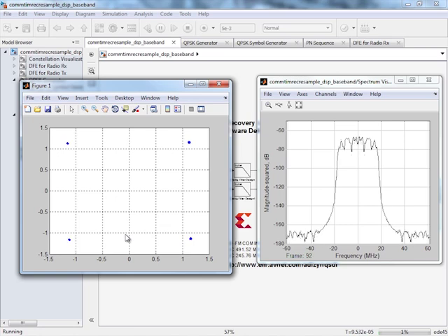However, a real communication system includes data converters as well as the accompanying analog circuitry, including RF transformers and analog filters. The analog signal is also affected by the channel, whether over the air or even just looped back through cables, as we're doing in this demo. Furthermore, the interface between the FPGA and the data converters must be designed, which is not a small task for the high-speed data capture of hundreds of megasamples per second. Presently, none of these effects has been accounted for in our Simulink model, but those are certainly elements that can be added to the model for a more detailed simulation.